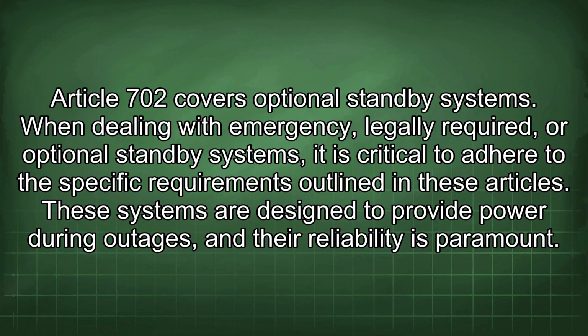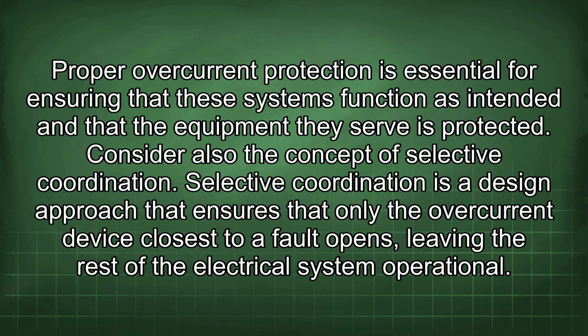When dealing with emergency, legally required, or optional standby systems, it is critical to adhere to the specific requirements outlined in these articles. These systems are designed to provide power during outages, and their reliability is paramount. Proper overcurrent protection is essential for ensuring that these systems function as intended and that the equipment they serve is protected. Consider also the concept of selective coordination.